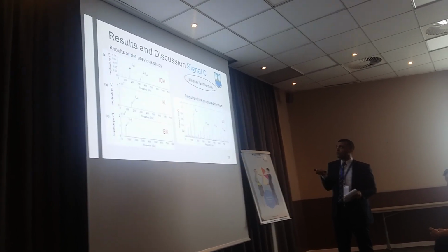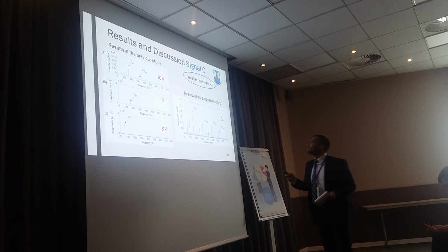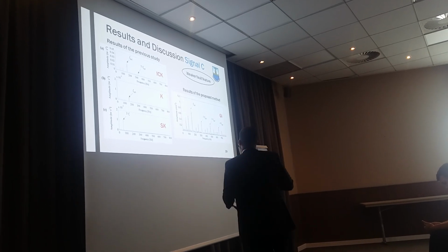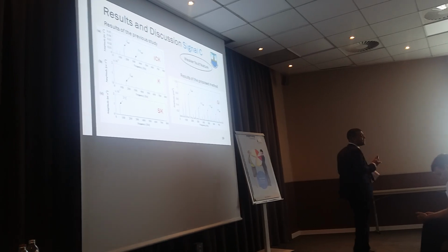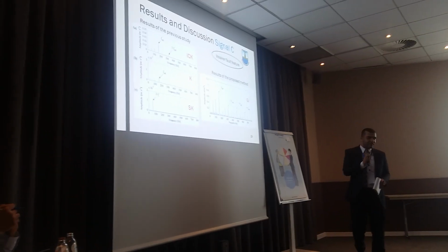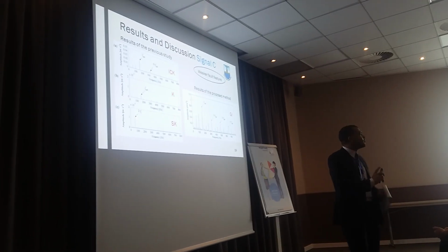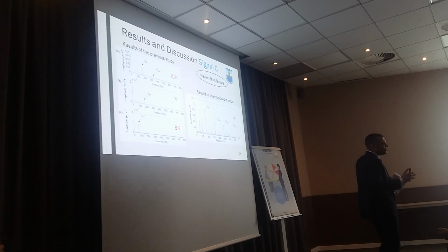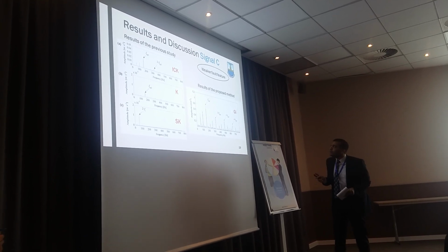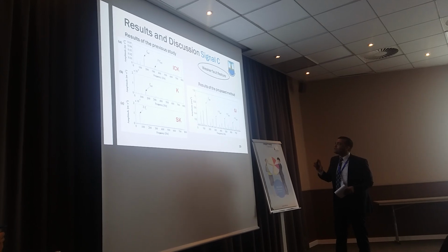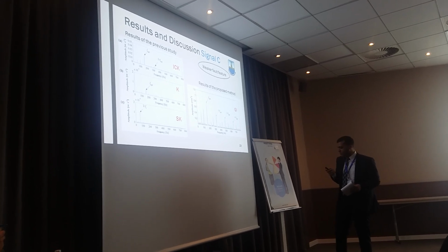And you should know that it's known in bearing diagnostics that it's proper to detect at least up to the third harmonic of the bearing characteristic frequency in the envelope spectrum. It is a known rule in bearing diagnostics. So I have up to the fourth harmonic.